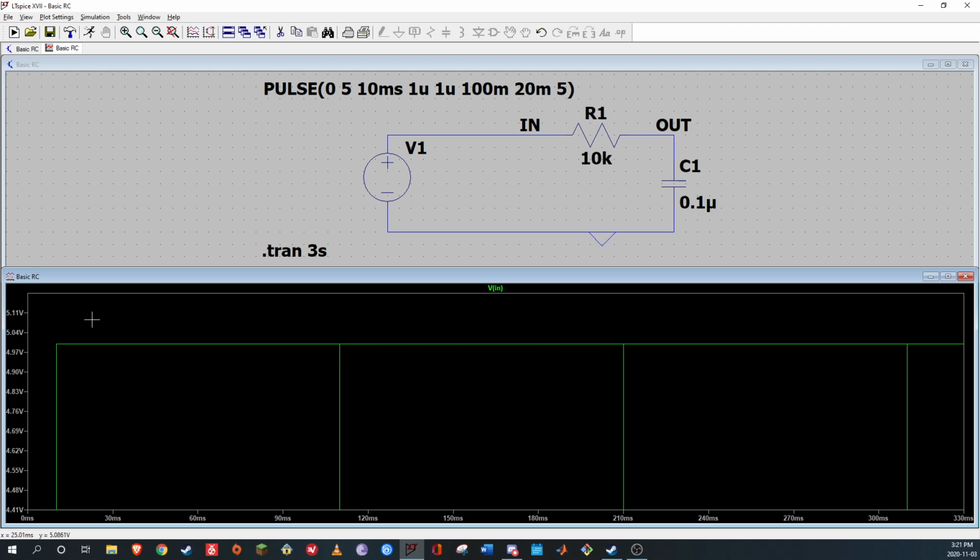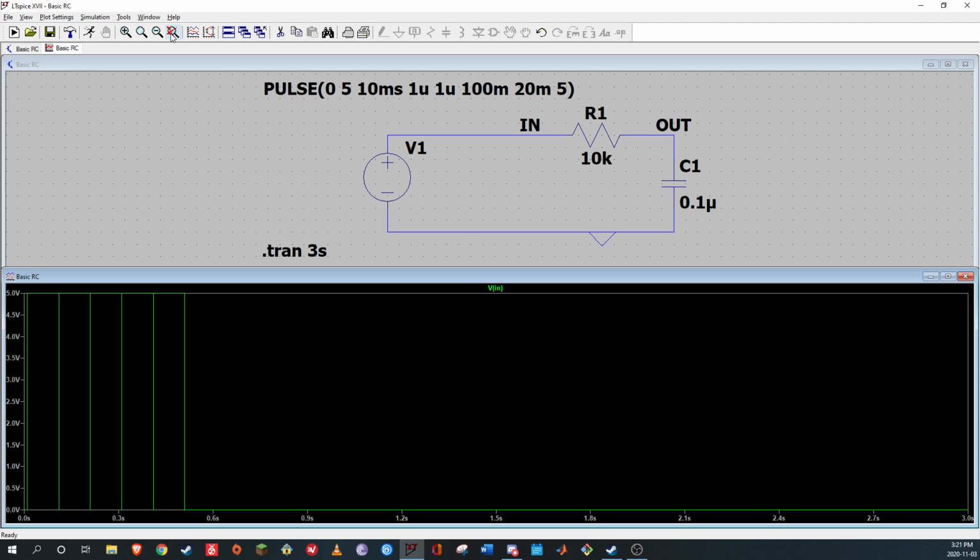It's making it so that it's on for longer than the period of the pulse. So it has a pulse, but it also has a period where it's just on anyway. So you don't want that. You want your T on to be at least less than your pulse.